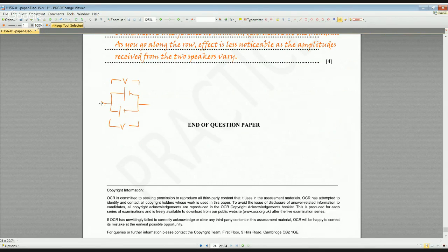So actually, if you connect a resistor across here, that resistor will have the same voltage no matter how many batteries we put in parallel here. The same is true if we put in loads of resistors. So anything in parallel, same voltage or same EMF.